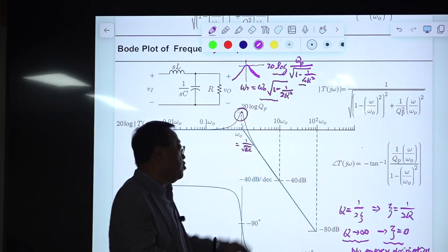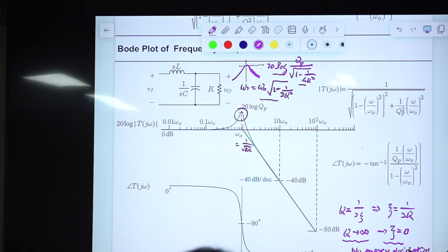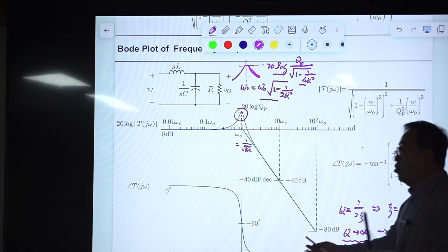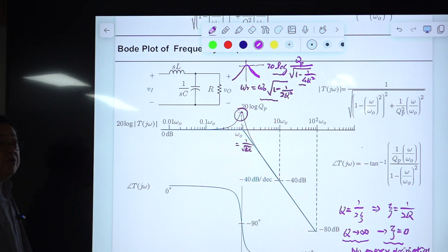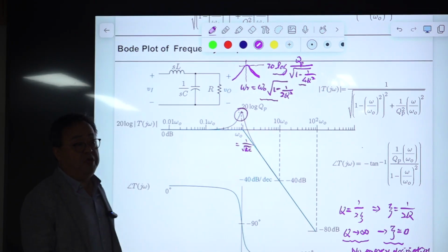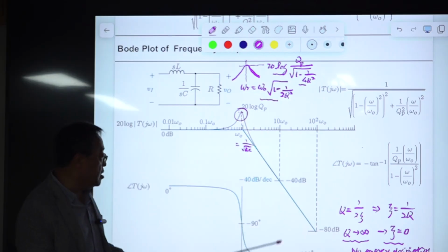For the resonance converter, which uses this lossless energy resonance, high Q means better operation as a converter. For the resonance converter, high Q is the desired one, and for the PWM converter, some number between 2 and 4 is desired. That makes the difference.